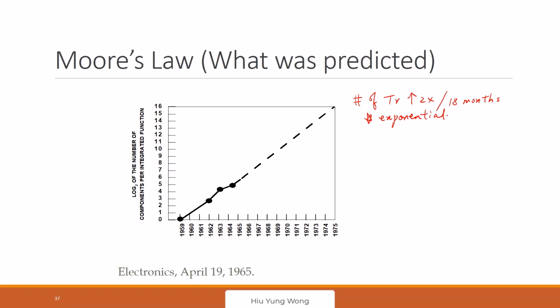I cannot put more transistors in this way. Just like what Omid just said, the Dennard scaling fails because we cannot continue to do that. We are going to have gate oxide being too thin, a lot of tunneling, junction being too steep, a lot of band-to-band tunneling, a lot of leakage current, reliability issues, power consumption issues.